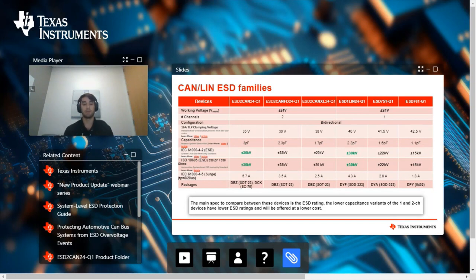And depending on the environmental conditions in the factory and how the cabling is handled, these discharges can get up to 30 kV and permanently cause damage. And this could also happen if a mechanic is performing maintenance on a car and has to disconnect and reconnect this cable. So in summary, anytime the cabling is manipulated in the system, there's going to be a chance for ESD.